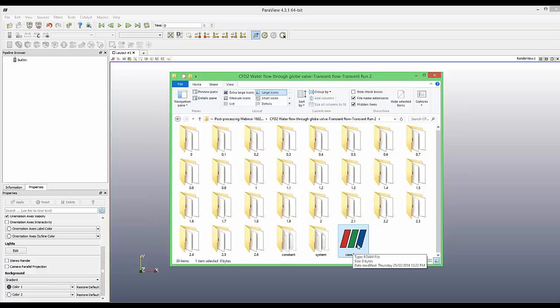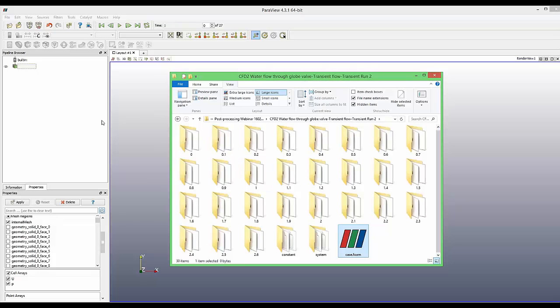We're using OpenFOAM as the CFD tool, so this particular file will define that the folder with the data contains a structure resembling OpenFOAM data. For structural analysis, we will have VTK setups. And I will simply load this into ParaView.